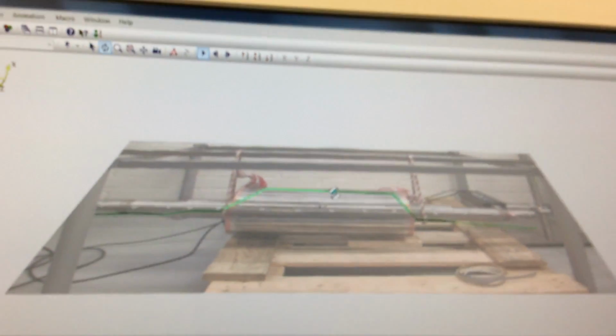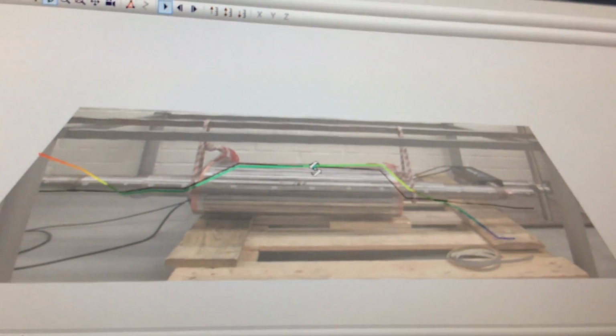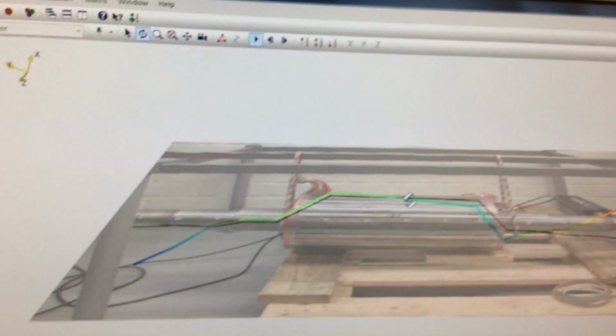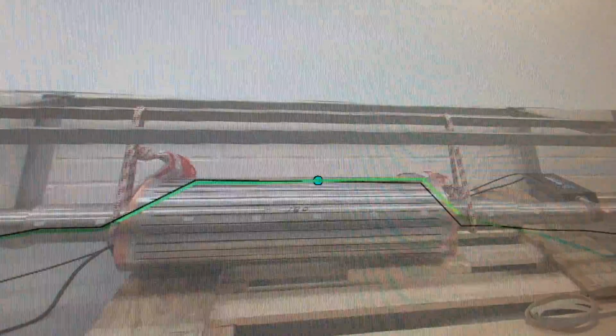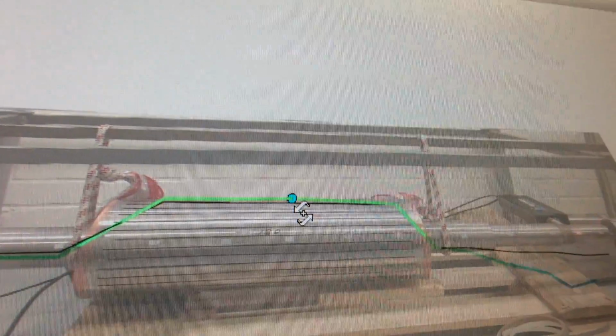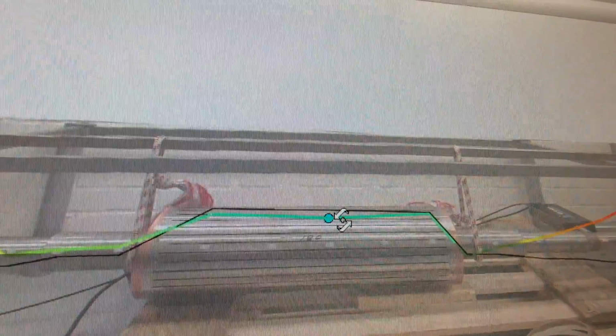This is another important analysis I want to show you: which points can be excited with a different amplitude. You can see that the end of the shaft goes up and downwards with a really large amplitude, but in the middle it's almost zero. That's for the second mode, but again, if I go back to the first mode, you can see some deformation in between. So it's not a bad point to measure the first frequency.